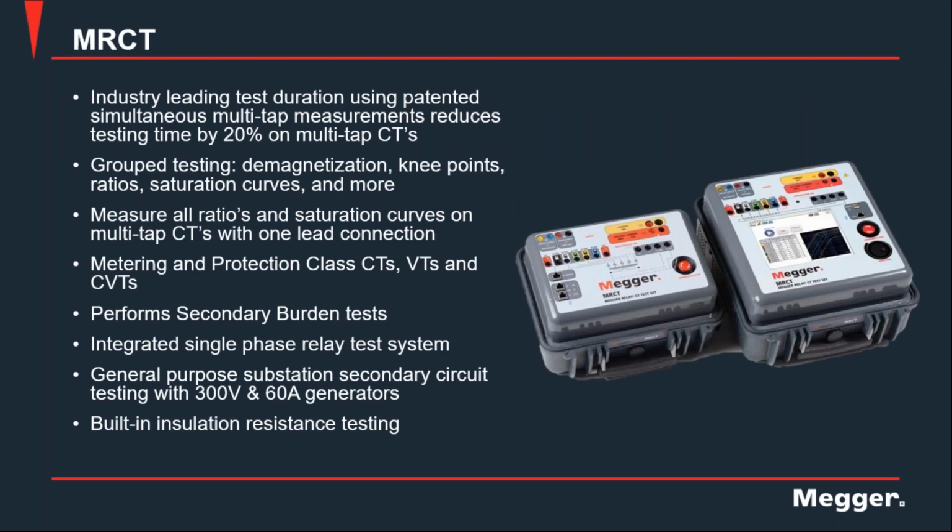Of course, we have instruments that can do all of these tests. We have the MRCT, which is an instrument that has a patented method of simultaneous testing, the concurrent method. And well, you reduce the time of testing drastically. It's also an instrument that can perform tests on all types of instrument transformers, CTs, VTs, and CVTs as well. And it has metering accuracy, with also the possibility to test relays with this instrument.